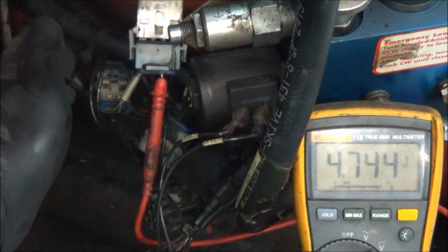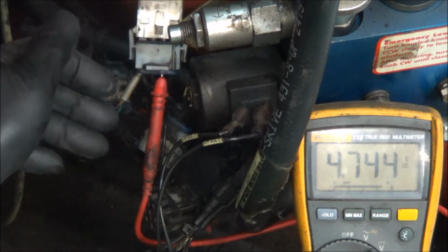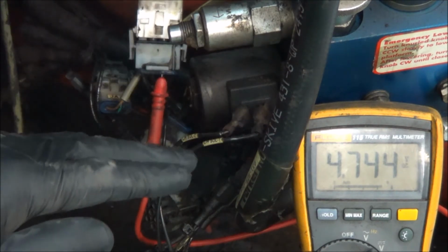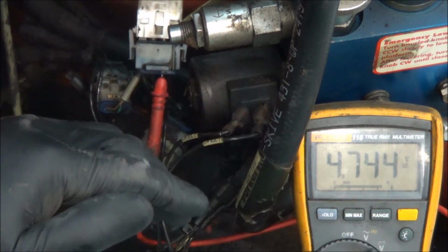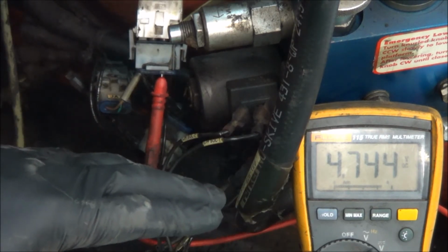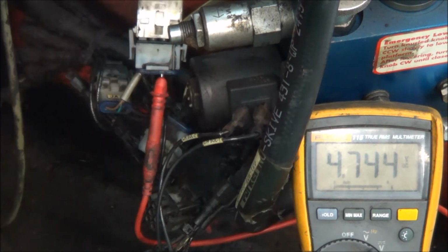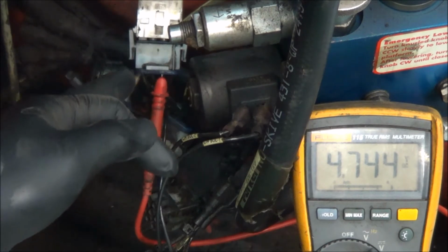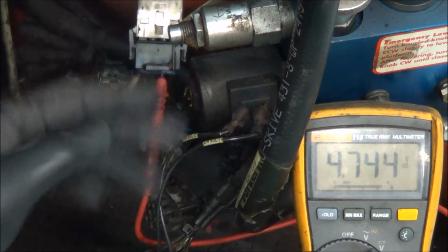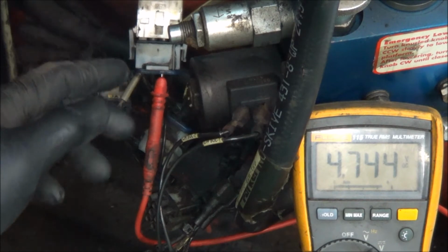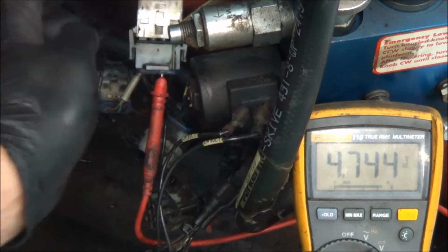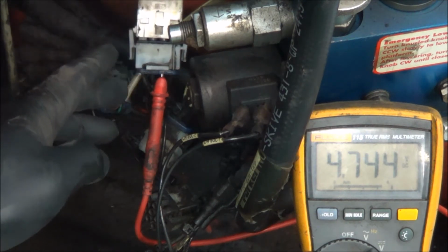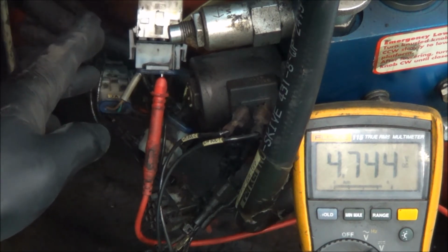So with the oscilloscope earlier, we saw that this channel was always at 5 volts and was never moving, so it kind of wants to move, but it couldn't reach 0 or negative, right? So this is how we're going to do this. We want to test if our signal wires, channel A and channel B, leading to the computer is good. So the other channel, which is the white, where I have the blue trace hooked up earlier, it was at dead zero. It was never moving, right?